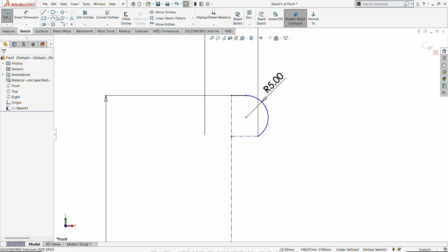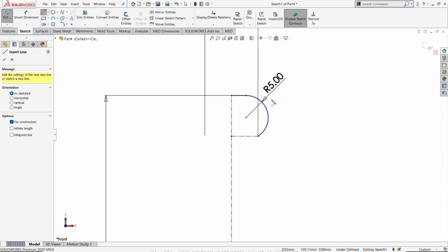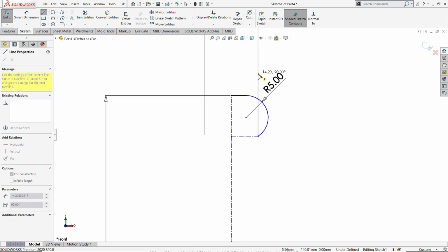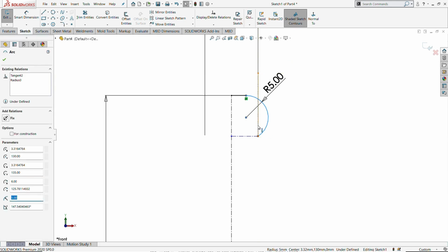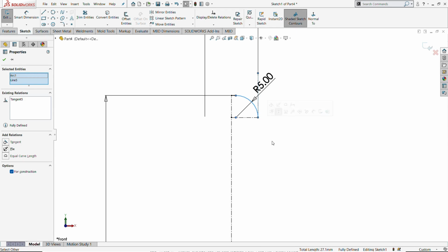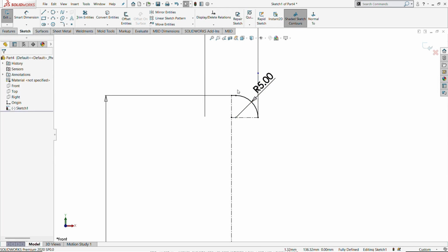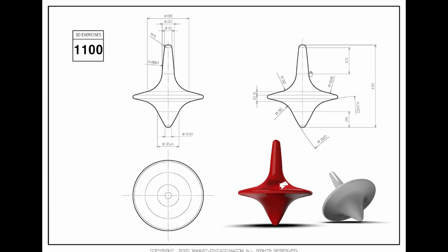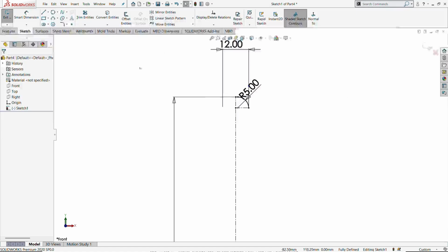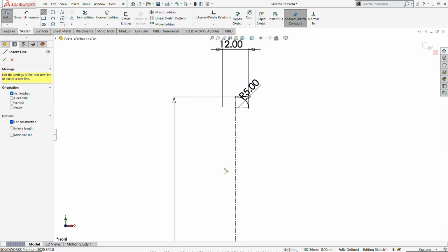Afterwards, again I am going to draw one vertical center line in this area. Afterwards, we are going to make tangential constraints on these portions. So select this arc as well as a line to make a tangential constraint. Once we form the tangential constraint on these portions, now draw one simple line profile. Look at this portion: the diameter of this area is 20 mm.